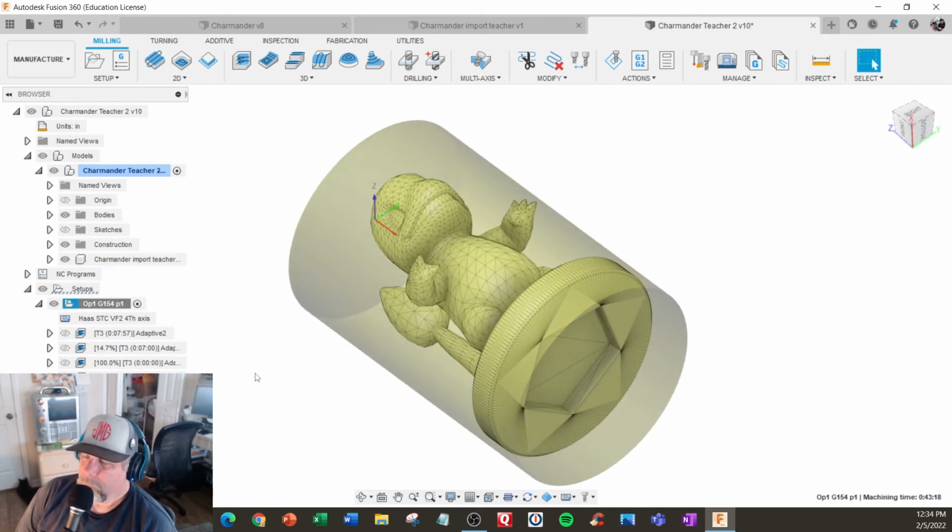So, all right, let's go back to it. A lot of this simulation time is dependent on if you select too many things, it's going to slow that down. Like if you're doing rest machining, it's looking back at other operations. If you're doing a lot on your adaptive setting, like stay down levels, that's more calculation time. So if you set everything loosey-goosey and you can get through your calculations, then you can start plugging in more stuff to make it faster machining but slower generation time.